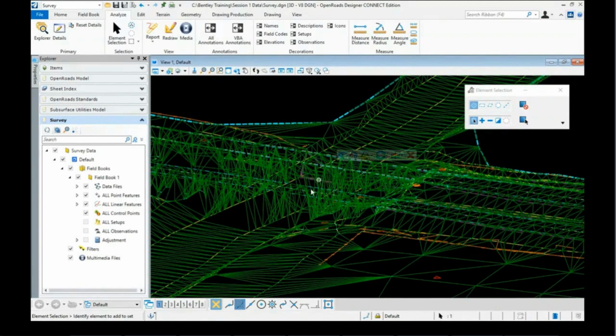In this case, I just want an existing ground topo here. If I want a terrain out of those, I can come in later and create a terrain from graphics by choosing those. But right now, I don't want those included in my existing ground terrain.